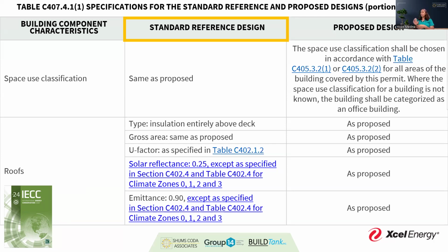A couple of the tables are going to change because, as we had mentioned last week, in the past for the commercial, the R value was the first compliance path that was in the book, and then the U factor, C factor, F factor table was the alternative. That's flopped. So now it's the same as it is on the residential side, where the U factor, C factor, F factor is the primary compliance path, and then the R value is the alternative.